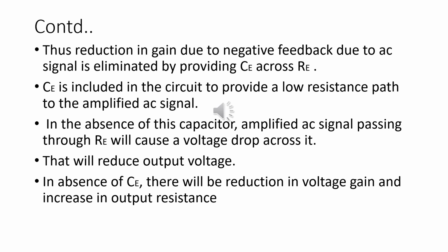So simply we are bypassing the current through a path which contains a capacitor rather than flowing it through a path containing resistance. So here we are bypassing the current flow. That is why it is known as the emitter bypass capacitor.